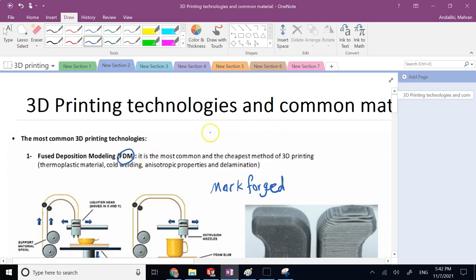They have the metal powder, like the SLS or SLM. They have the metal powders in a spool. So they have a spool, and most of the time the spools these guys have is not like a plastic like this, right? That's not the kind of spool that they use. The spools that they use, or the feed they might call it, is a rod. So it is a rod, and what's inside this rod is a bunch of what? Is all of these metal powders.